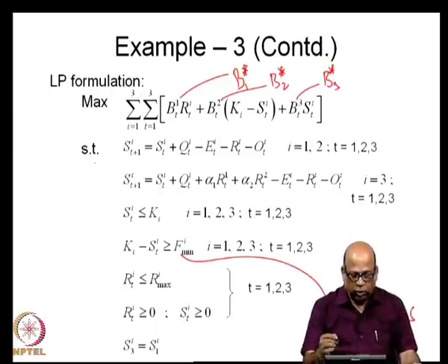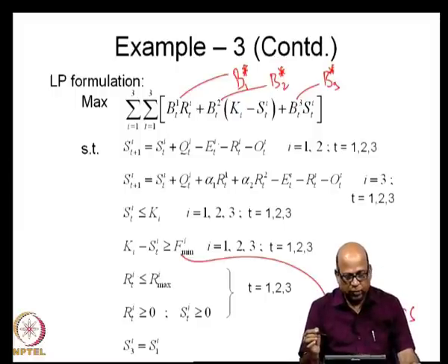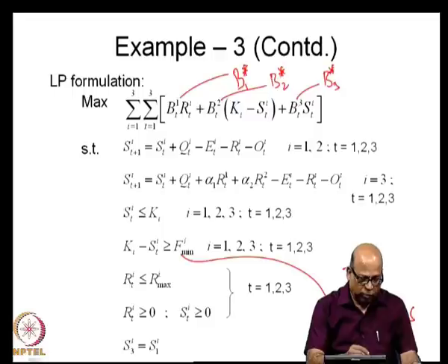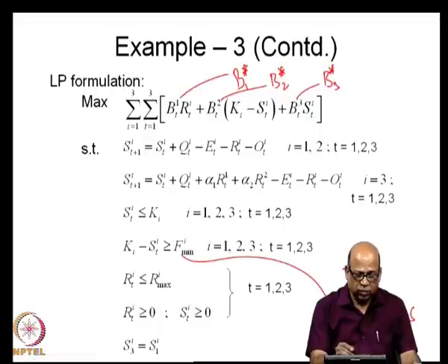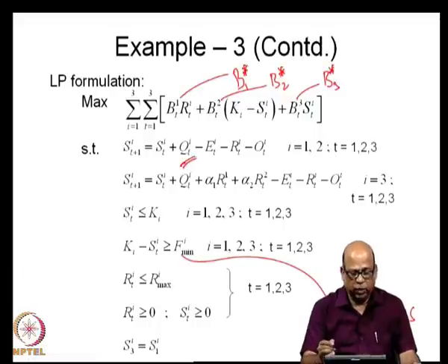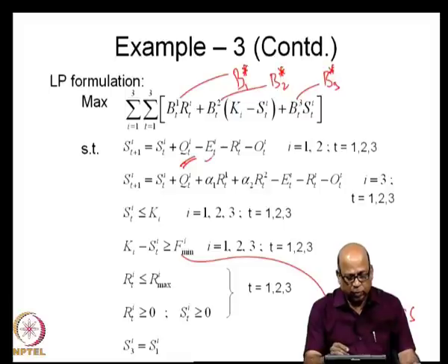So, this is the model that we will solve for the example given earlier. What is the data that will be necessary here? The flows at each of these reservoirs, this is the inflow, this should be given. The evaporation rates may be specified. If you are ignoring the evaporation, then this term does not exist, and then you have to specify the storage capacities.